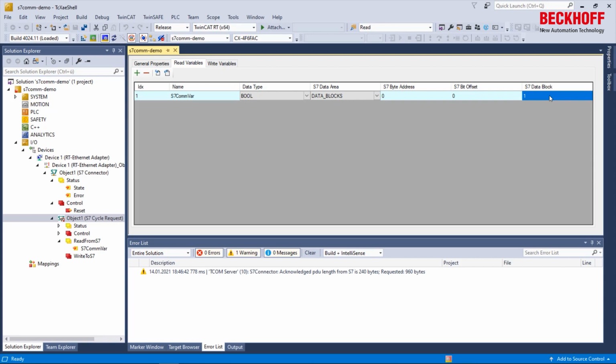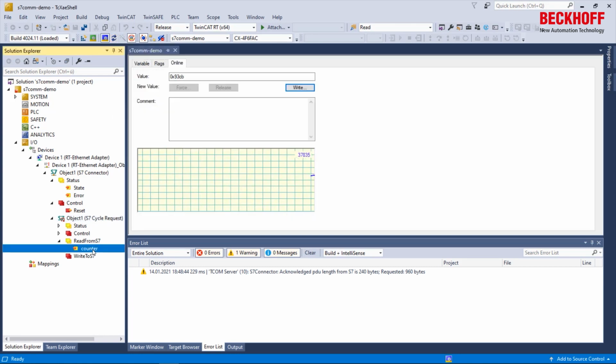Now we can read an actual value. The Profinet coupler contains a cycle counter as the process data. Data type is word, and we find the counter in the input data area. And the address is, in our case, 256. Okay, I click Reload Devices and we watch our value. And yes, the cycle counter increments as we expected.